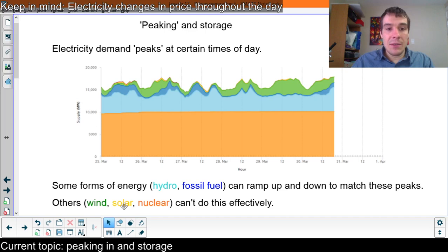You can't do that with solar and you can't do that with wind. It's harder to do with hydro at speed. Hydro is harder to spin up the turbine than these guys are to react. So it's faster. And so we still have fossil fuel burning power plants, mostly for this peaking that they can do here in Ontario. So that's peaking. You can see the solar. There was some solar here and some solar here and some solar here, but not a lot of solar here when it was rainy over the weekend.